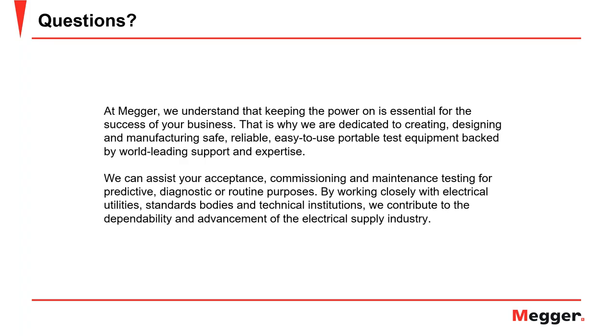When the amount of reactive power taken by that synchronous motor becomes too high, then you have what's called an asynchronous operation, which again is the consequence of the loss of synchronism. So that's another option that you have when it comes to protecting against the loss of synchronism. Like I said, I'm only going to discuss these options. There are many out there that you can find.